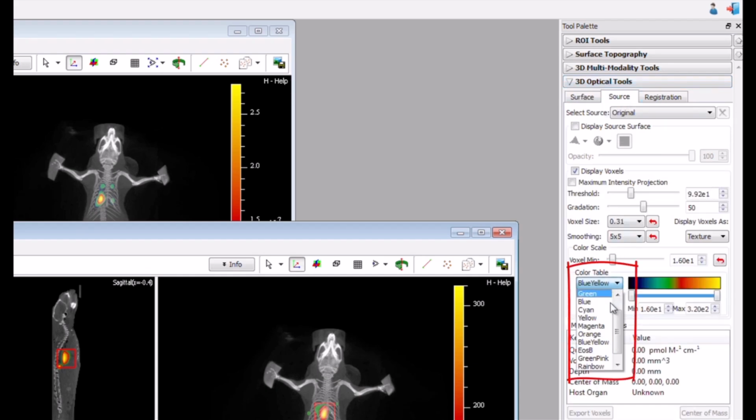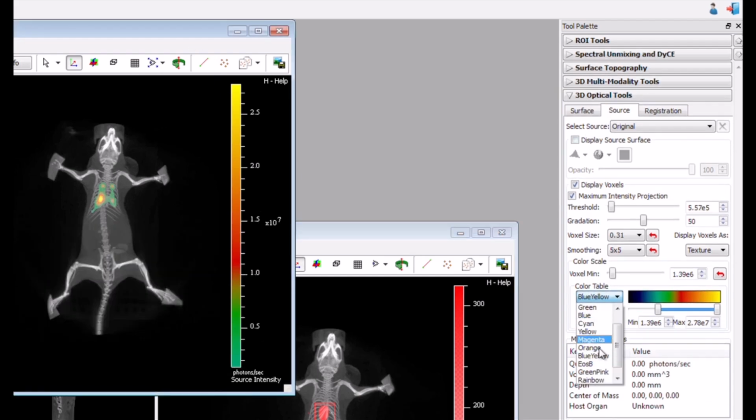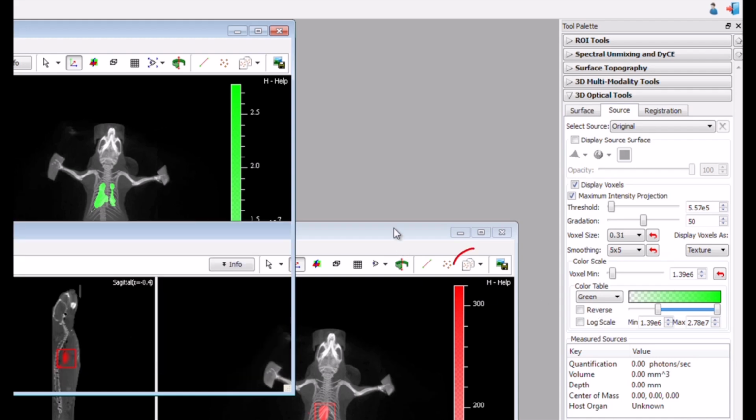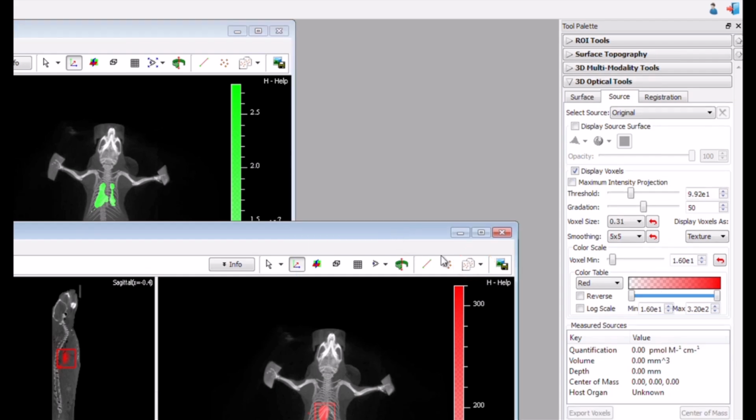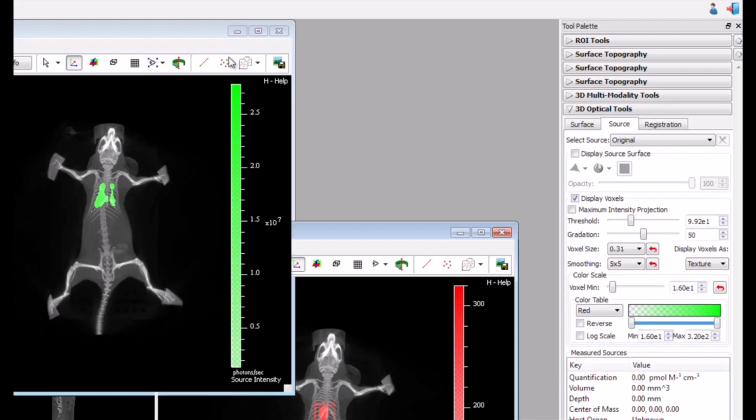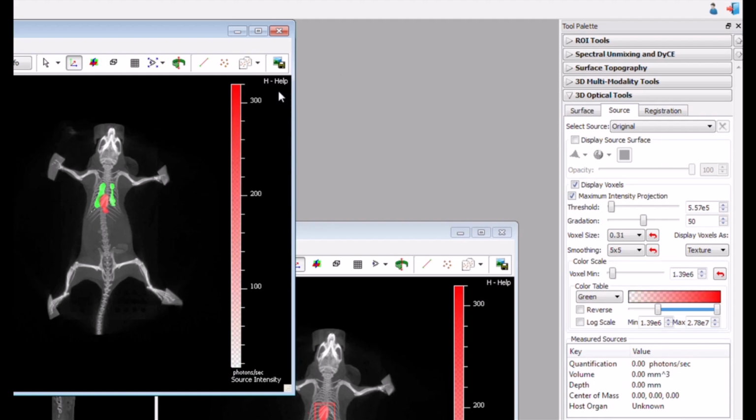We select the Source subtab and choose Red from the Color Table pull-down. The same process will be followed for changing the DLIT data voxels to green. With the DLIT data and FLIT data now easily distinguishable by color, open the FLIT dataset window, click on the Copy-Paste button, and select Copy Source Voxels. The FLIT data has now been copied to the clipboard. Now open the DLIT dataset window, click on the Copy-Paste button and select Paste Source Results.